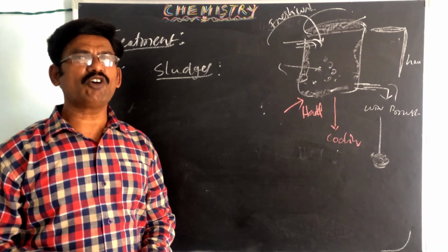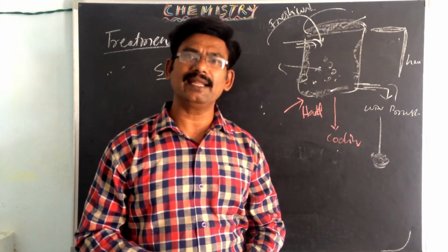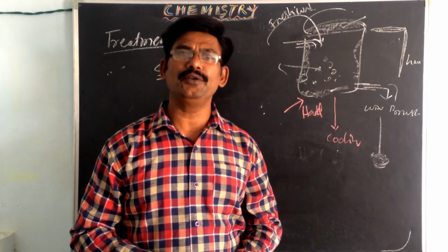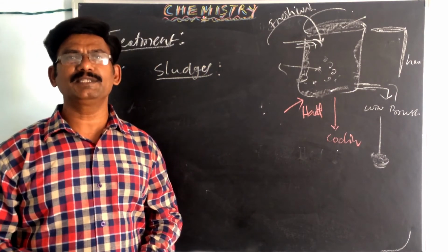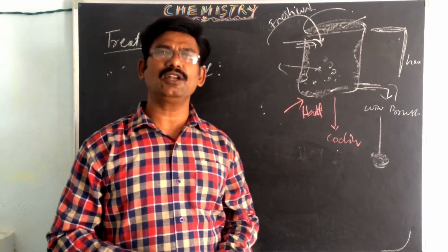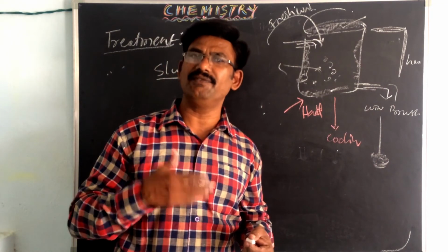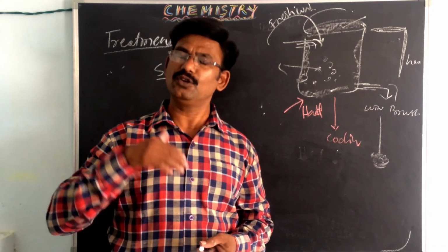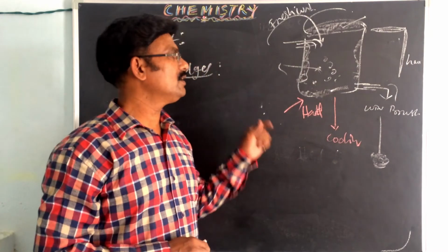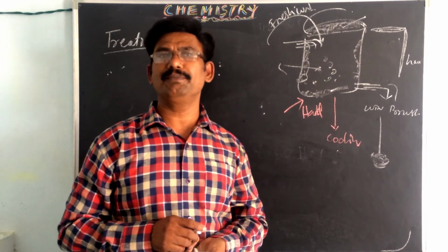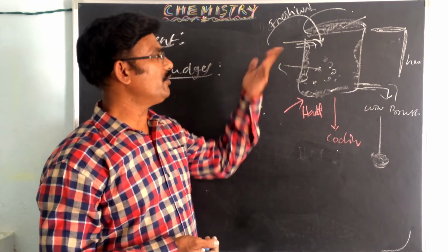Next, by using softened water, that is, treatment of water before entering the boiler for reducing the concentration of scale-producing ions. This process is also known as external treatment. External treatment means the ion exchange method, which we will discuss in the next class or further classes. After purification, pure deionized water is used in the boilers.